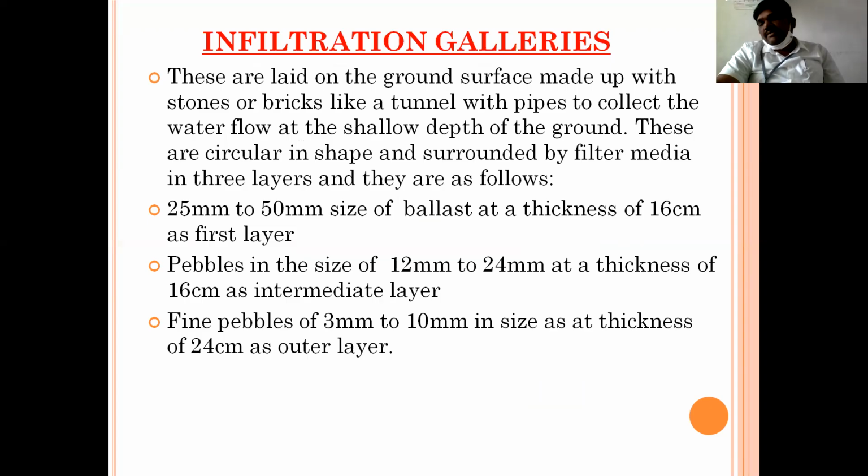You understand what I said? One more time. These galleries are constructed at river banks. River banks, in the sense, not all river banks. Only at the river banks where plenty of groundwater is available can these types of infiltration galleries be constructed to meet the requirement of water.